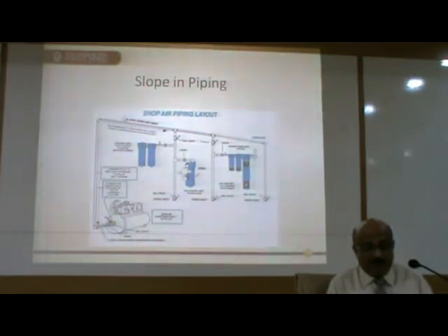If the length of the pipe is high, then instead of making joints, welded joints can be made, so that a single seamless pipe length can be installed instead of unnecessary bends, which will give frictional losses and ultimately affect the efficiency of the compressors.